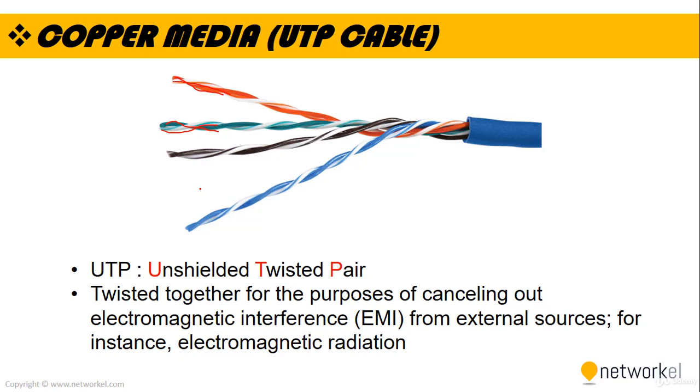The two individual wires in a single pair are twisted around each other, and then the pairs are twisted around each other as well. This is done to reduce crosstalk and electromagnetic interference, each of which can degrade network performance. Each signal on a twisted pair requires both wires.